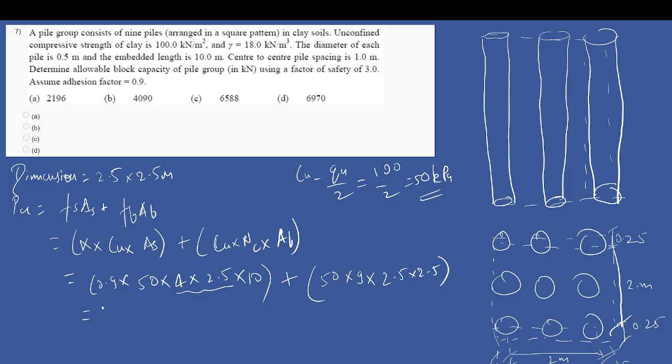1312.5. 73112.5. Okay, even I've made a mistake here. Since this is not your strip footing, this is basically the square foundation, so instead of multiplying with 1, there's another factor which will come, 1.3 times Cu Nc.